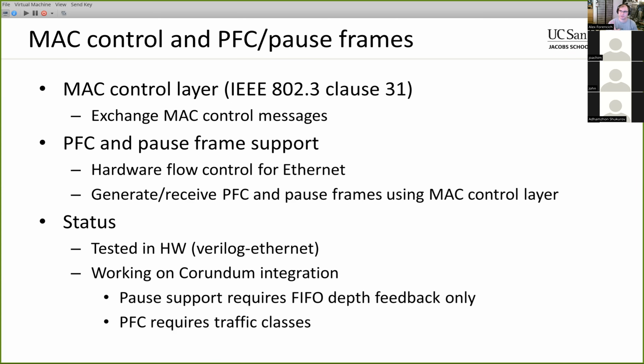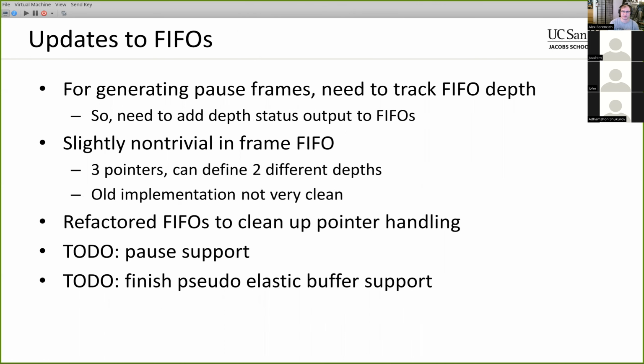But dealing with PFC requires implementing traffic classes in the data path at various points, and actually generating pause frames requires feedback of the depths of some of the transmit FIFOs. So I'm going to take a crack at getting that working first, but obviously there are a few things that need to be implemented along those lines. So that's the current status there.